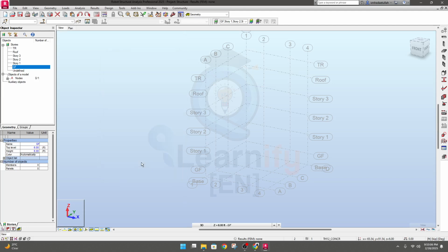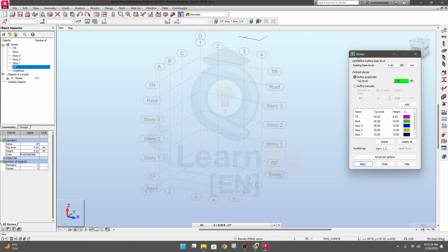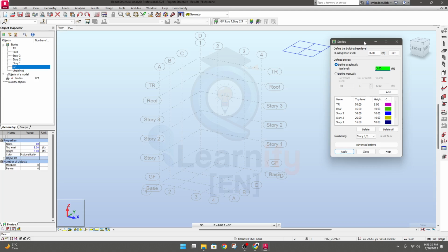I will close. Now let's say if you need to create or increase another story here, how will we do it? To do it, I'll go to define manually. Let's say take its name terrace, no problem, and its height will be 46 feet.